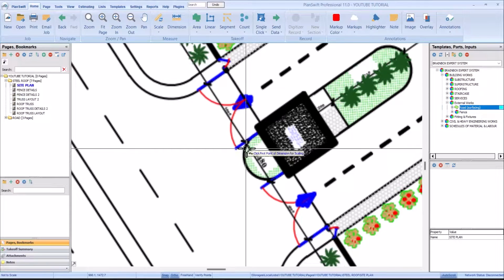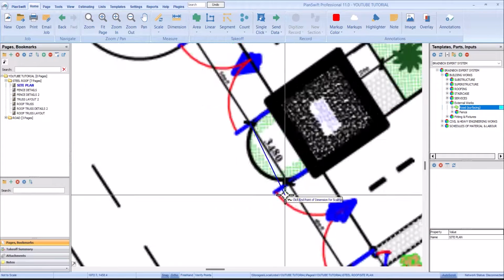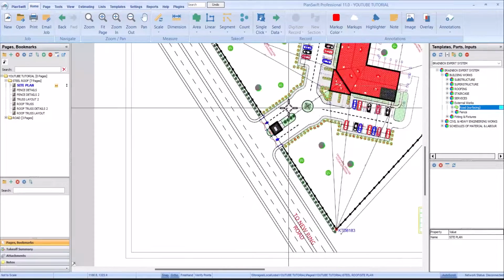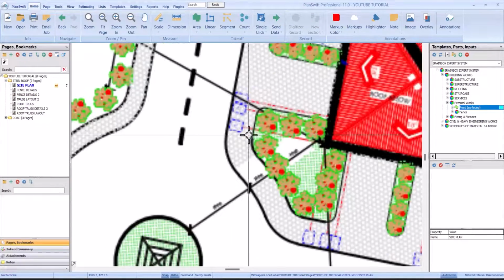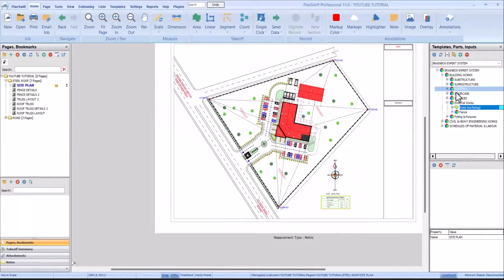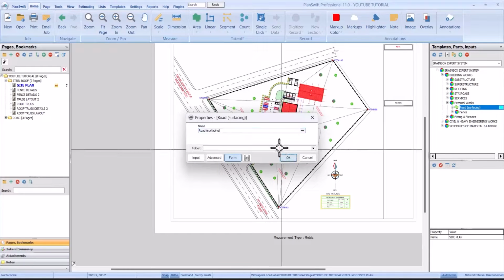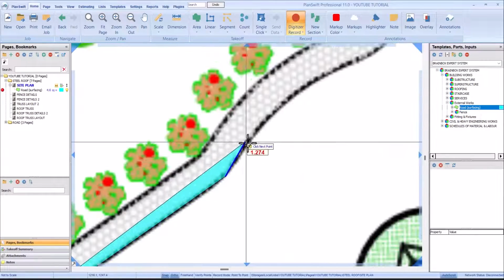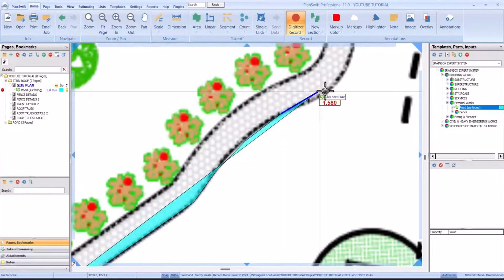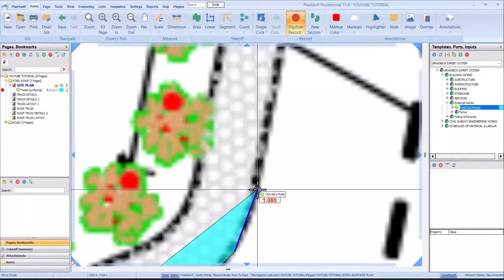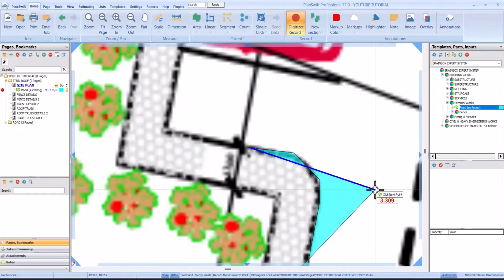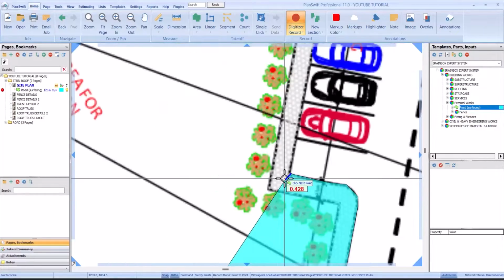3.48. Click OK. I've scaled our drawing. There are other dimensions, but this one is okay. We can now start our takeoff for the road. Go to zoom and follow the edges carefully.